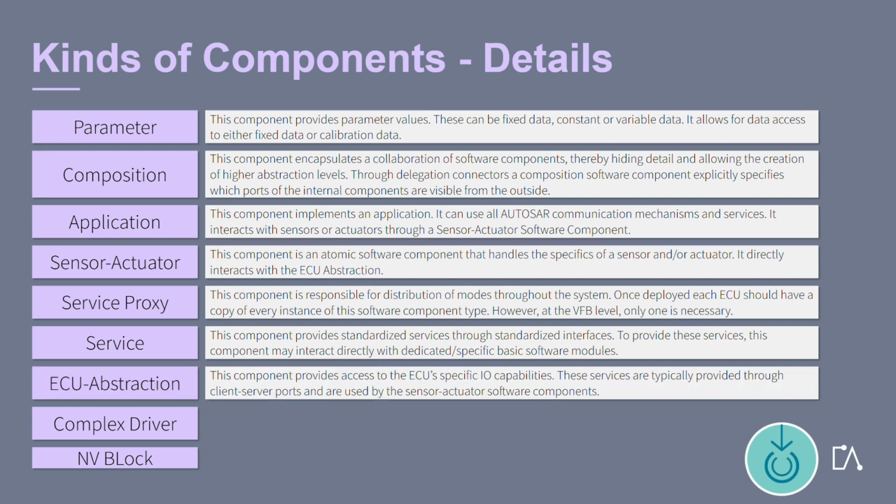The ECU abstraction component provides access to the ECU's specific input-output capabilities. These services are typically provided through client-server ports and are used by the sensor-actuator software components.